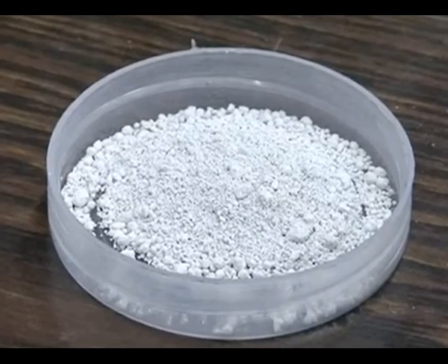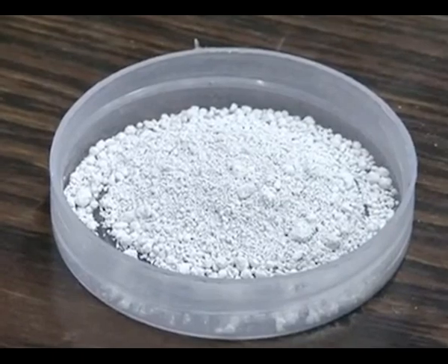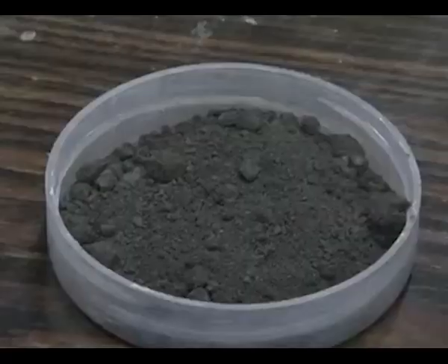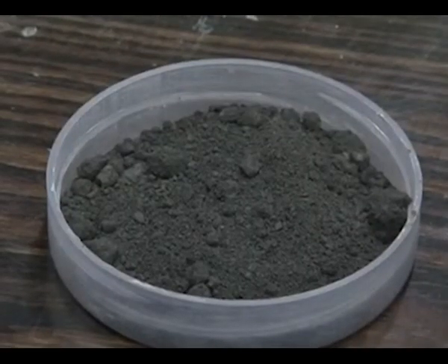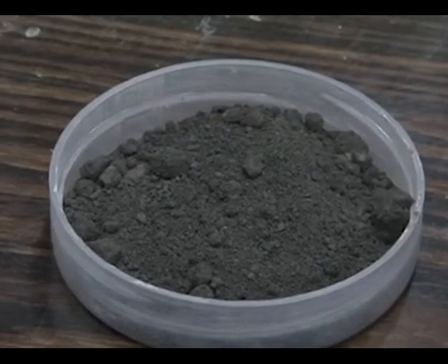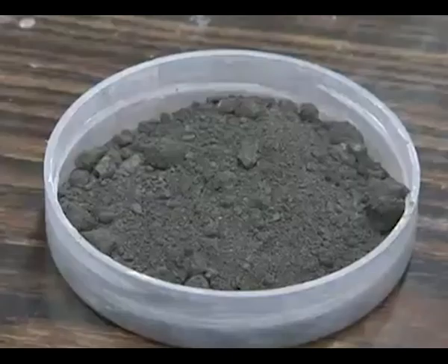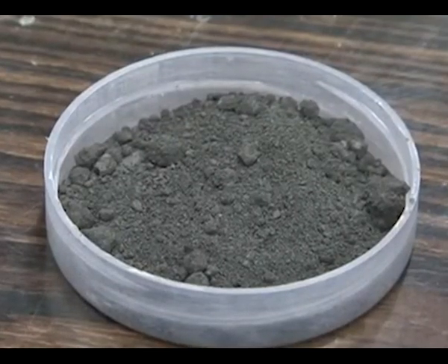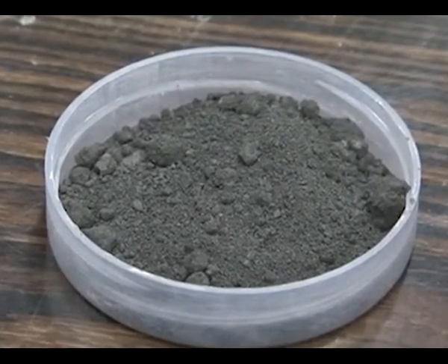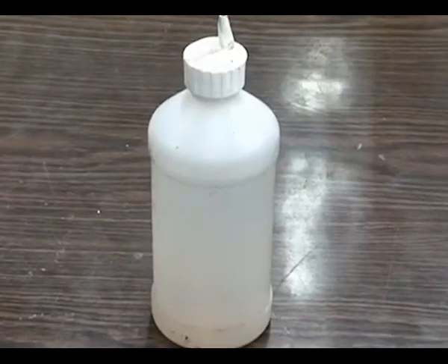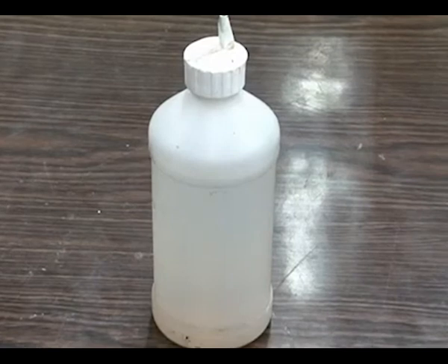Abrasive particles are required to increase material removal, in other words to reduce finishing time. In the present case the abrasive is aluminum oxide. Carbonyl iron particles, in other words magnetic particles, are required to make the MRF fluid stiffen under the effect of a magnetic field. When the magnetic field is applied, iron particles are aligned along the line of the magnetic field and they create a dense structure. Water is required to provide a liquid medium so that magnetic particles as well as abrasive particles disperse uniformly.